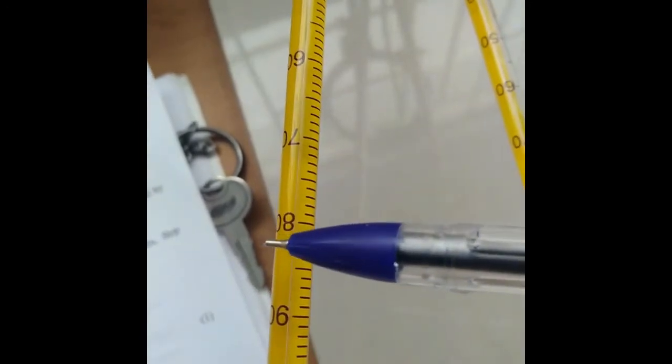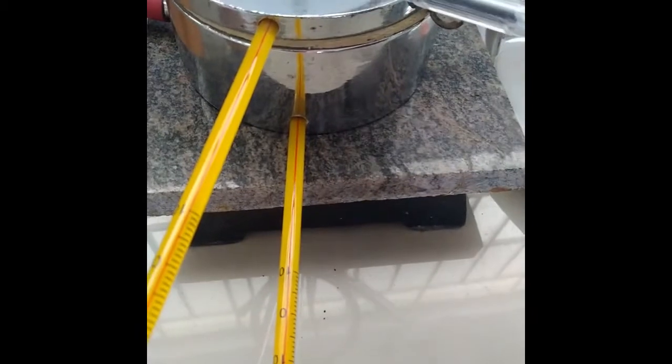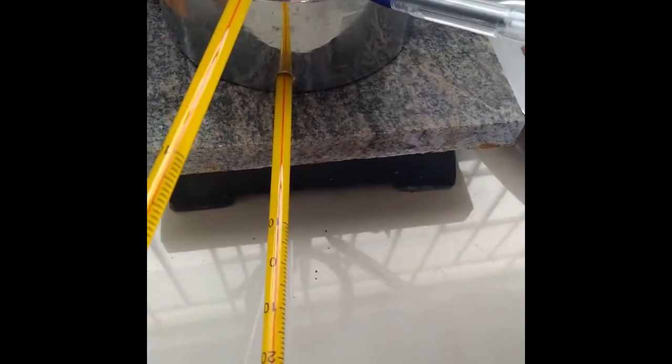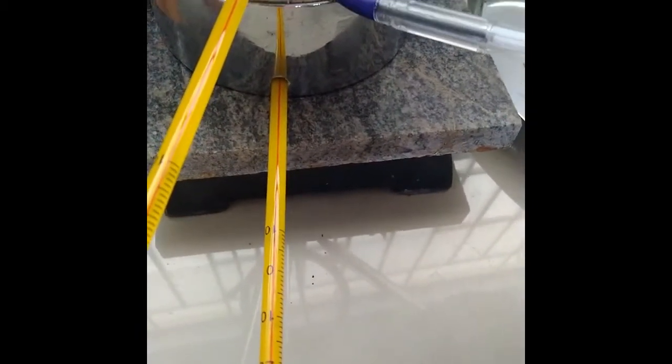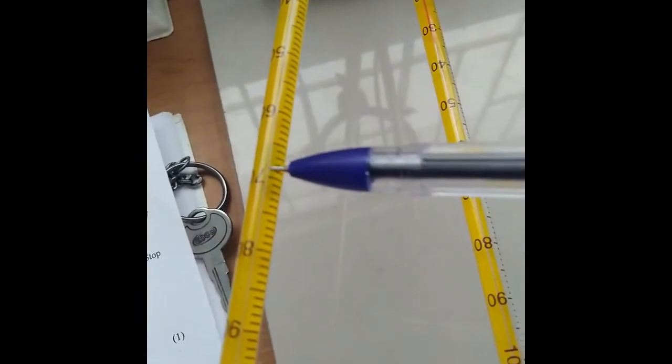Why does it happen? Because there is a bad conductor in between the steam chamber and the Lee's disc. Depending upon the thermal conductivity of this bad conductor as well as its thickness, the steady state temperature of the Lee's disc will stay around some 80 degrees Celsius, right? So after a steady state is reached by the Lee's disc, note down the temperature on the thermometer in the Lee's disc as the steady state value, right?